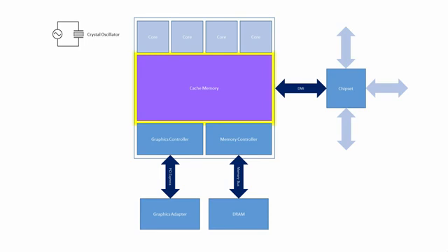Another significant change to the overall architecture is that the North Bridge chip no longer exists. The memory and graphics controllers are now integrated into the CPU chip. This removes the need for a front-side bus between the CPU and the RAM, which has had a huge impact on the performance of modern PCs. The South Bridge is also gone.